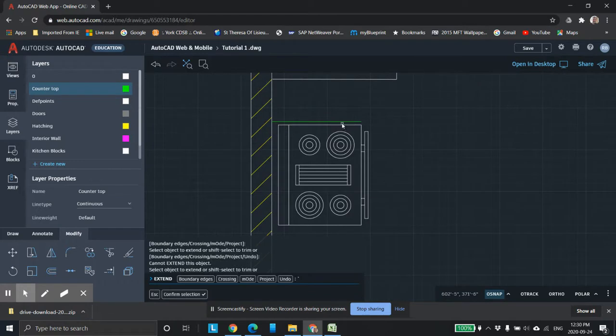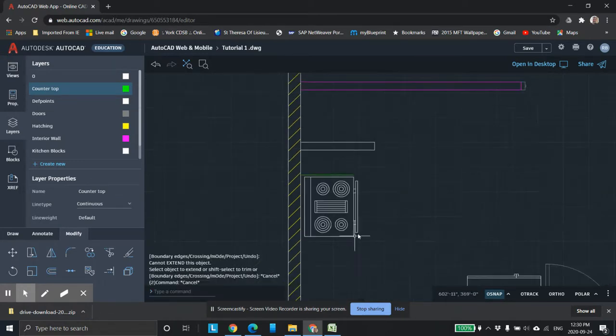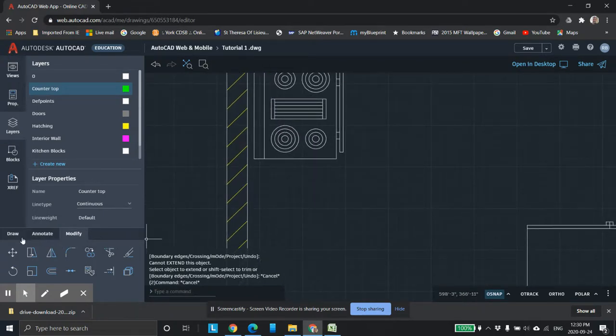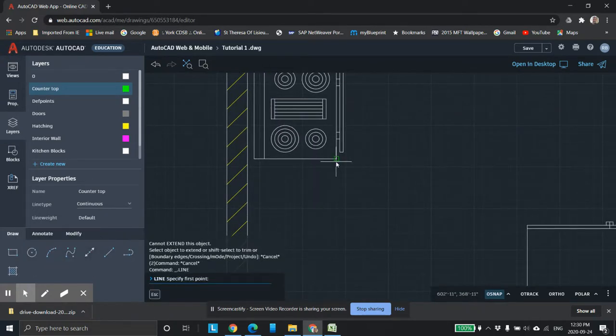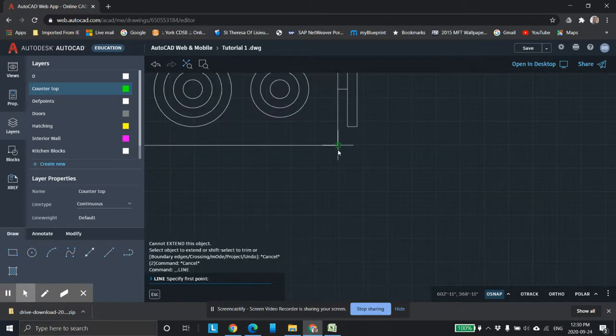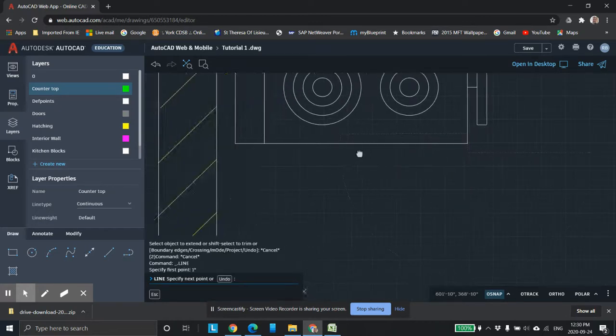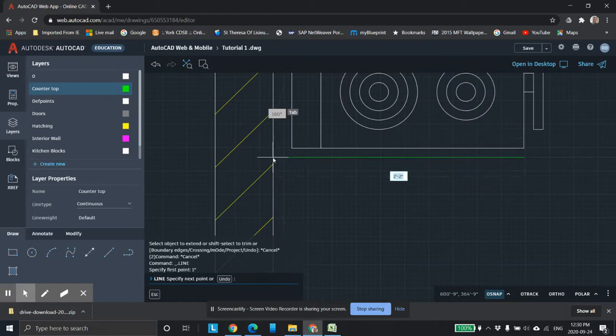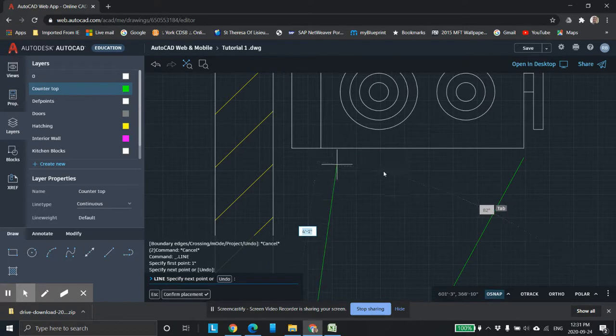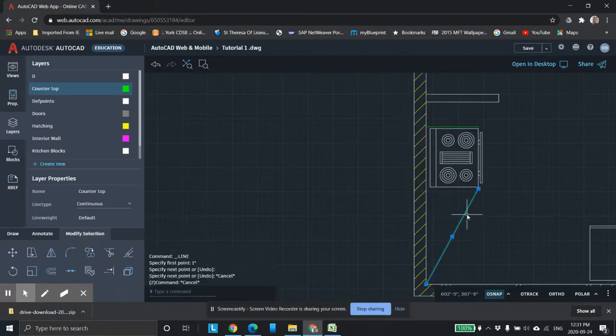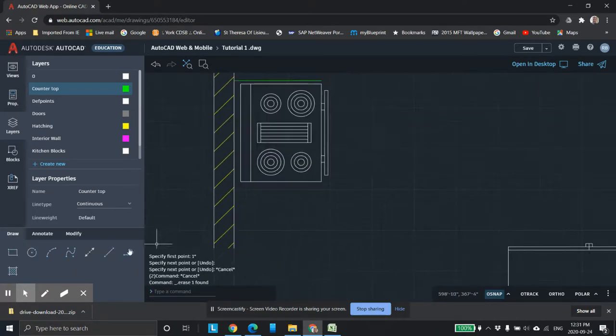Now I've got a 1 inch gap here, and I'm going to put a 1 inch gap on the other end as well, down here. And the reason I'm going to do that is the same thing. If there's any variation in those stoves, I don't want to have to cut my granite or go and get a smaller stove. 1 inch, enter. Walk back in this way, and it grabbed, jumped down the corner. Let's try that again.